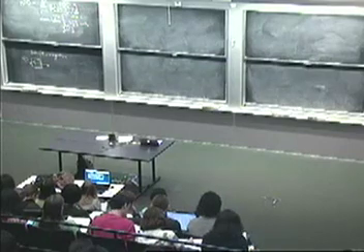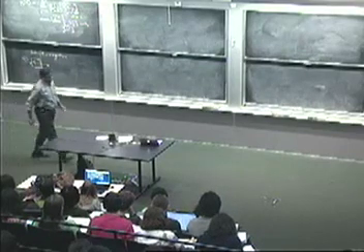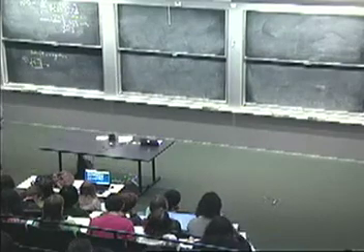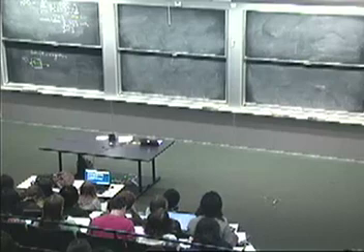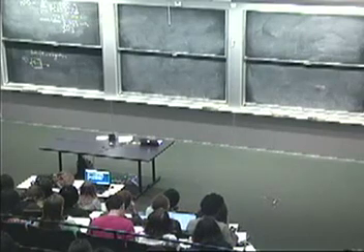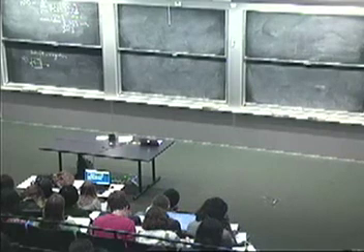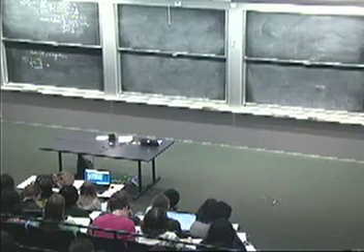Now, what you have up there is a cascade of shift registers. So you've got 2 shift registers. If you keep in mind the operation that I described, and I'm looking at this at time n with xn sitting here, what must be in this shift register is the input of the previous time, so that's xn minus 1.